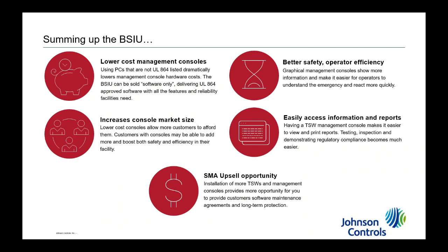Because the principle behind it is that anything that would cause the operation of the system to rely on the BSIU being up and running, or anything that would flow information through the BSIU to be acted on by the fire alarm system, those were the things that weren't allowed. In fact, we have a nice podcast listed on the Autocall website, the Industry Roundtable with Roger Reiswig, that if you haven't listened to yet, I'd recommend that you do. It'll really help you understand what the BSIU is.